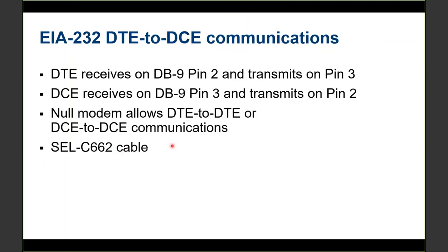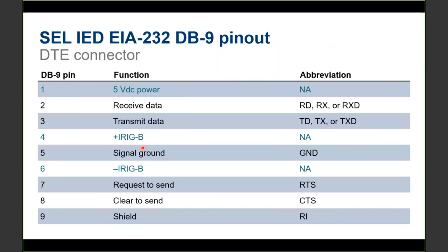And just so you know, you can run into trouble using some third-party USB to serial cables. I'll just warn y'all that you can run into some issues if the driver isn't up to date, and basically not every single cable does a good job of converting from USB to serial communications. And keep in mind that also is included in our warranty. The 10-year warranty covers those cables.